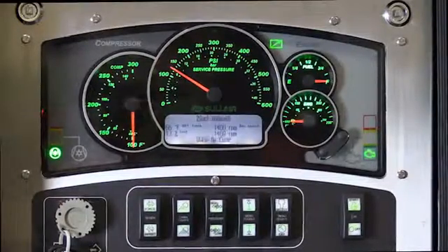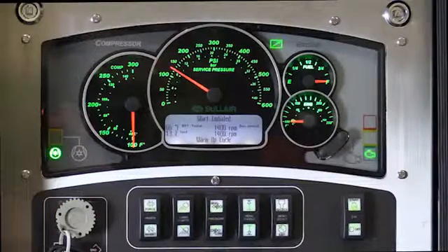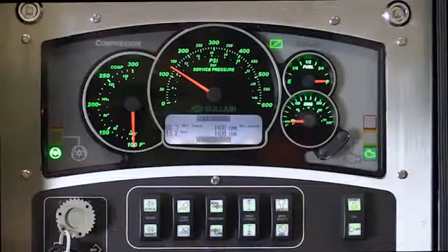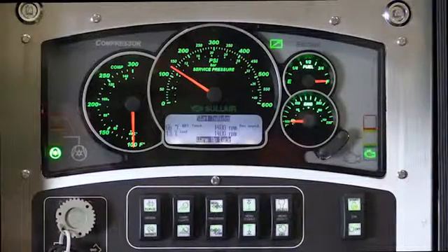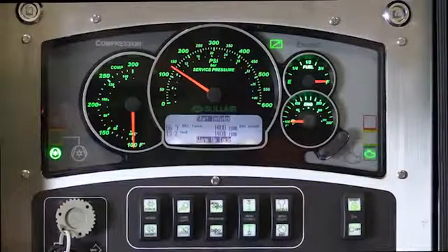Once the engine is started, the C-Pro controller goes into the warm-up mode. During this time, the inlet valve is held closed and idle speed is commanded to minimum. This keeps the tank pressures down, allowing the engine to warm up freely, and keeps torsional vibration at a minimum to protect the coupling.